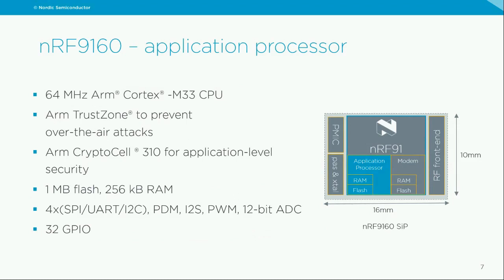And this means that it's possible to separate completely the software that manages security-related aspects of your application from all the software that typically contains a lot of stacks and middleware and a lot of open source code in today's world. And by partitioning the application in this way, the device doesn't become vulnerable to over-the-air attacks that typically go after weaknesses found in stacks and middleware.